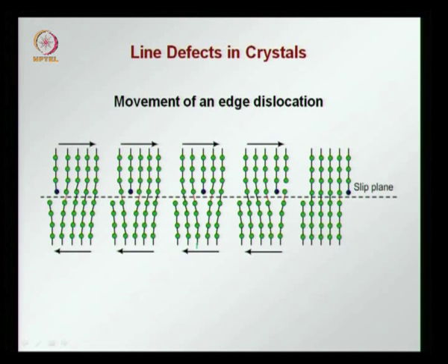These dislocations move under slip. So when you have here say a crystal lattice with a dislocation here, and we are trying to shear or make this zone slip, this dislocation now moves towards an edge. So you see here in these diagrams, one by one the bond is broken and created.